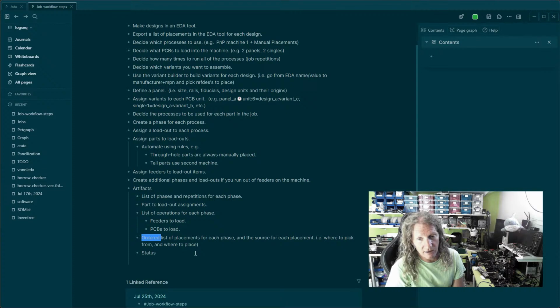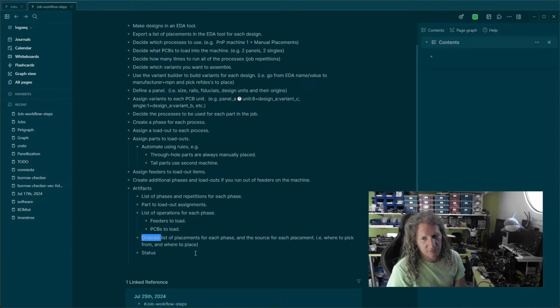The reason for that is so that you get your accuracy correct at the start of the job, and not realise after placing some large components on some large solder pads that your accuracy for your 0402s is bad and it's way off, but your accuracy for your 1206s was accurate enough. So I don't think we really need to go into ordering, but there does need to be some ordering.